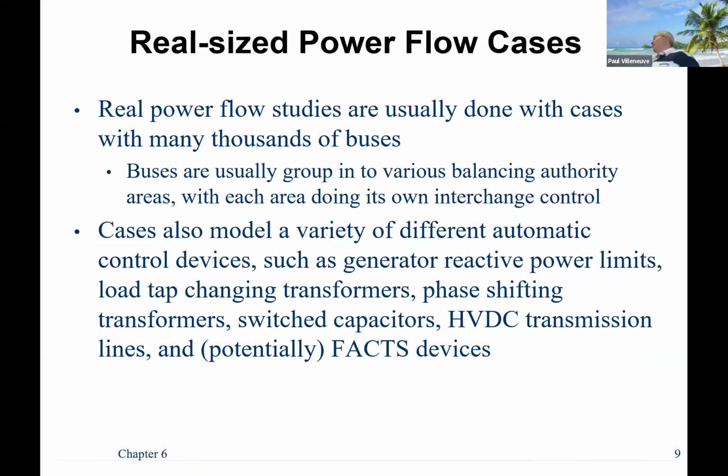And I worked on a distribution circuit in Sanford that actually had a capacitor bank that could be switched in and out, which is very expensive, because one of the things you have to be careful of when you turn a capacitor on and off is to do it at zero crossings, because if not, you can get crazy high transients. So switching a capacitor on or off is a very expensive proposition because you need what's called an independently pole operated breaker. Each breaker pole opens on its own time frame. That triples the cost of the breaker, way more expensive. So you don't see a lot of them, but there is one in Sanford that I believe is still operating.